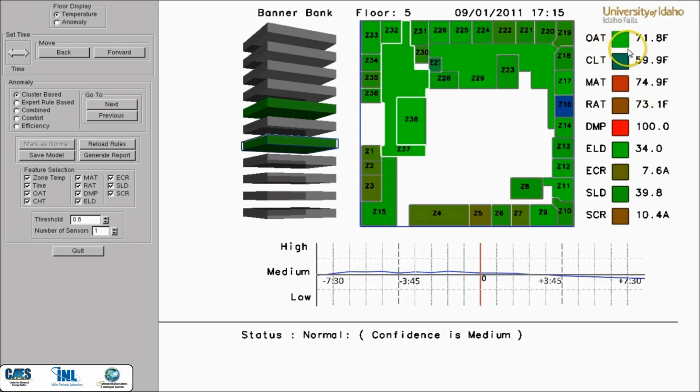Similar to flow and zone colors, the accompanying colored box indicates the current value of the sensor, where red corresponds to high sensor values, green medium sensor values, and blue low sensor values. The actual value of the sensor reading is also displayed along with measurement units.